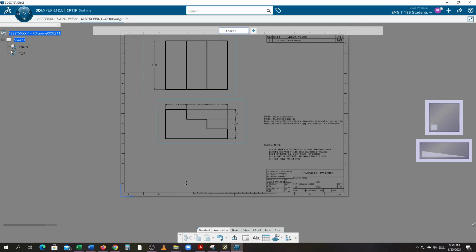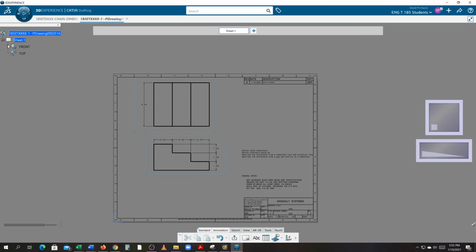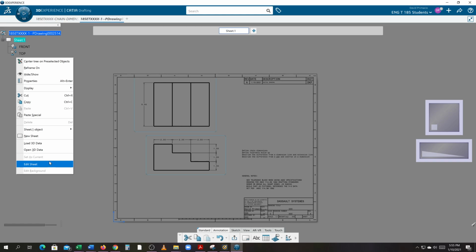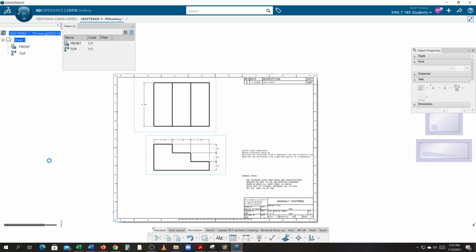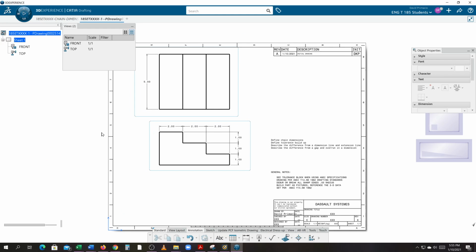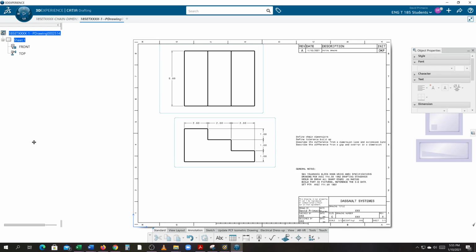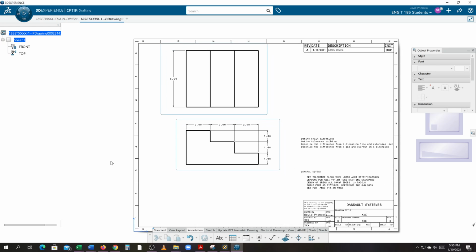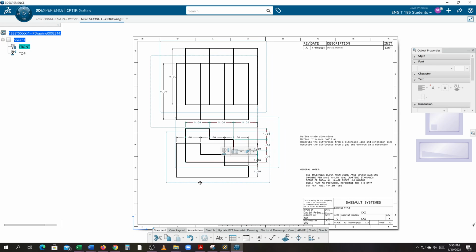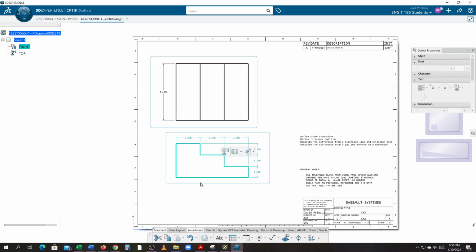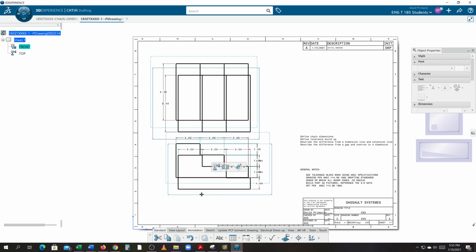Now you've got to create this drawing. Remember, when you're done, go back to Edit Sheet. Okay, close this off. This looks a little weird. Don't forget to title this. Move this view down here a little bit. You got plenty of room down here.